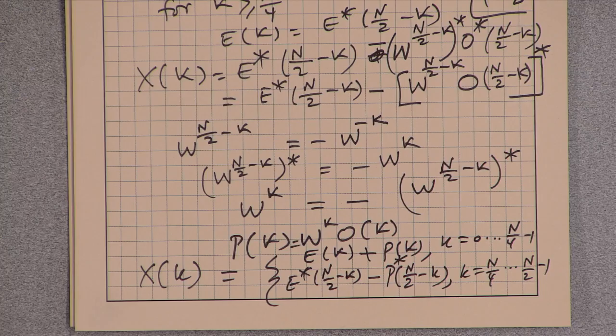Okay, so that's a little long process, but that's what the modems are doing. So they are computing the N point real FFT by N by 2 point complex FFT. Okay, so any questions?